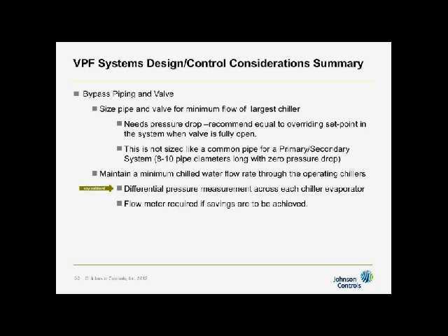I have 20 feet of pressure drop at 3,000 GPM through these chillers. If I go down to minimum flow, which for these chillers is 776 GPM, or just about 25% flow, then it's 0.25 squared. 0.25 squared is 0.0625 times my 20 feet, which means I'm at 1.2 feet.